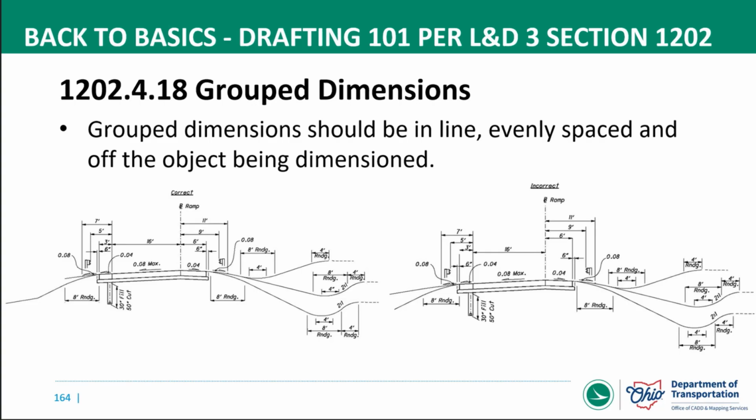And then last here is the use of the word typical, especially for symmetrical type drawings and details. We encourage that because we don't want to see all the extra annotations. Perhaps one of those dimensions or radii, one of these details changes, but you only change one side, not the other. So if we only label it one place, we don't have that redundant information. And it kind of just clutters up your drawing too.